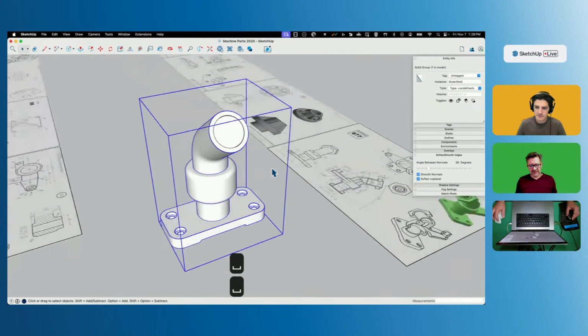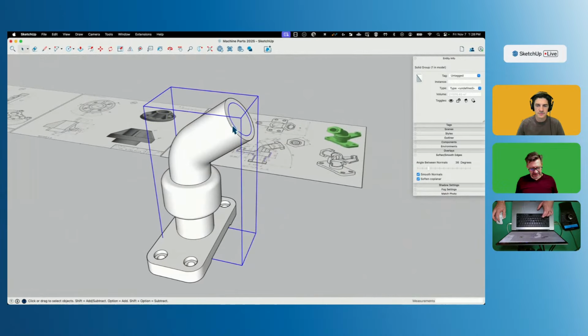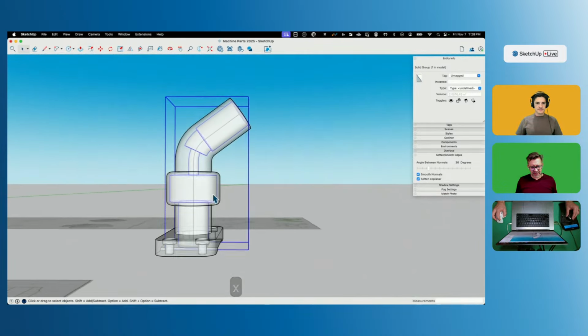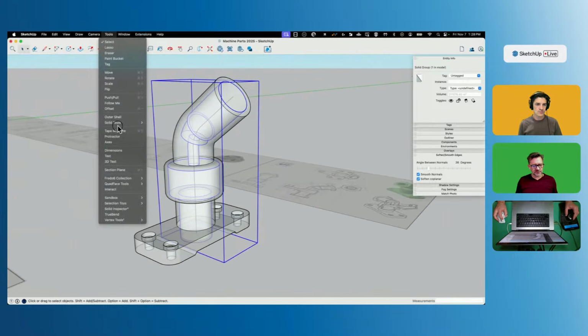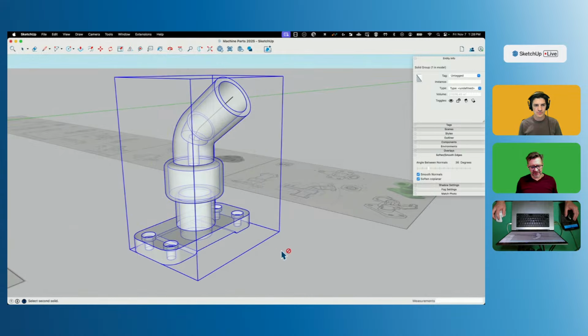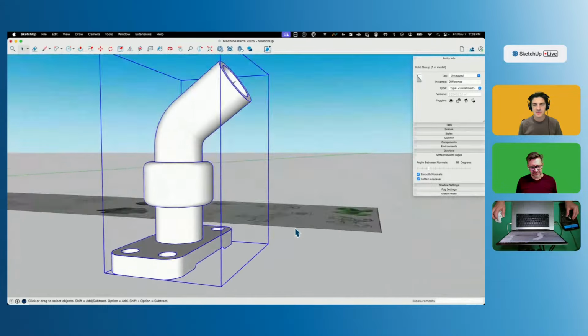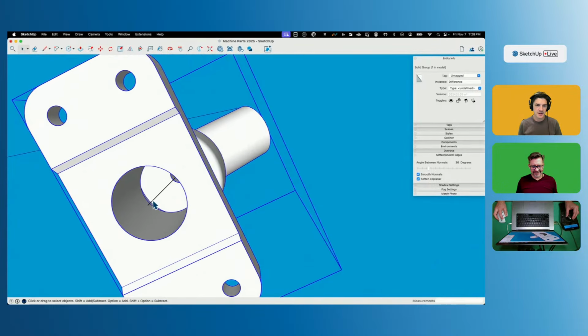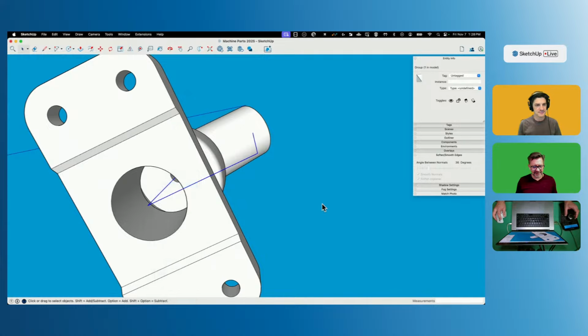It's good. My last step on this chunk is to take this piece and subtract it out from the larger piece. So I'm going to take that, Tools, Solid Tools, and I don't need to hold on to it, so I can just do a straight up subtract from here. And let's see how that looks. Very nice. Coming together, right. I'm going to keep this, but hide it.